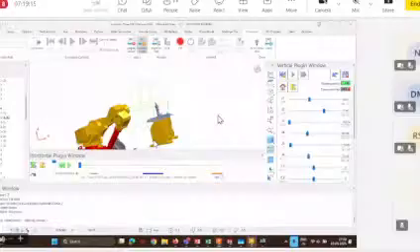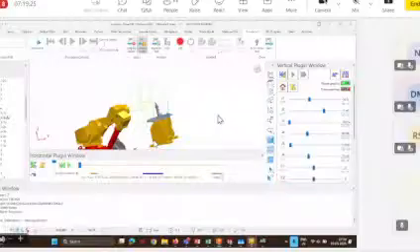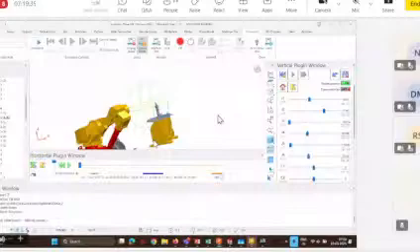You can see it's showing a singularity. There is an option for avoiding singularity also. If you enable it and rerun again, like this you can identify all the errors if there are any.